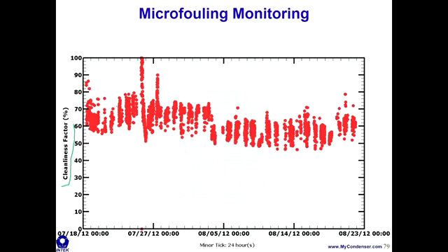Now you'll see that there's data missing in these time periods because all of this data has been filtered for only high load. This condenser is a peaking unit. It's up and down all day long, and so we've taken out the data that's below probably 90% load. And so here you can see this cleanliness factor over a month-and-a-half time period.